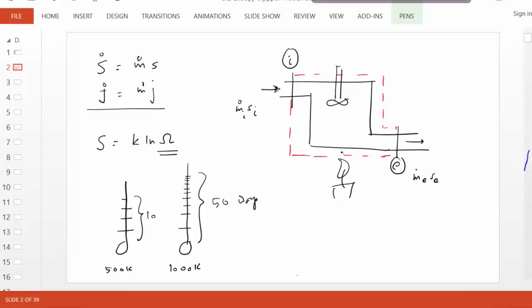What is even more difficult to understand is that the amount of entropy transfer is proportional to heat transfer, but it is moderated by the temperature of the boundary. In other words, if the boundary temperature is very high, the entropy transfer is a little bit less. Look at this relationship, inverse relationship. That's a little bit difficult to understand. One will think that if the temperature is higher, aren't molecules having more number of ways, how in the world is the entropy transfer decreasing in that case?